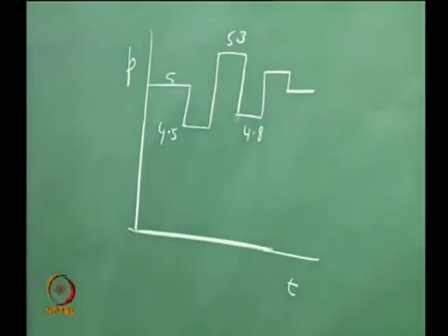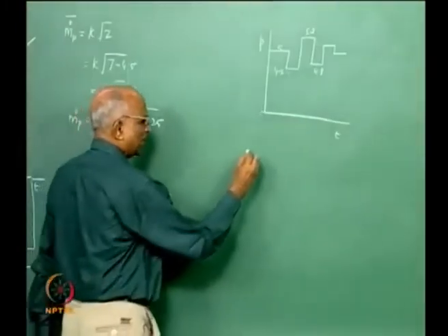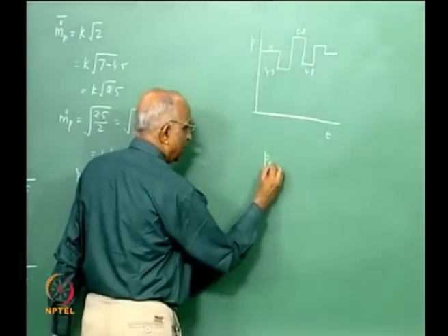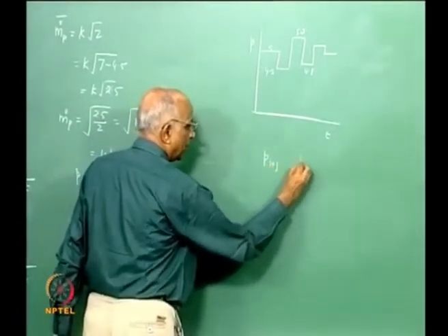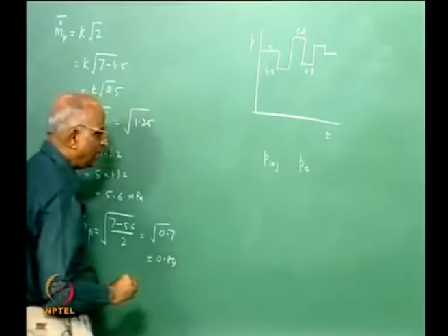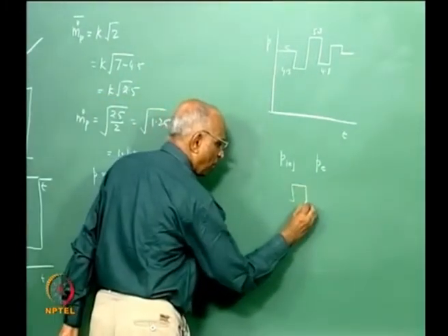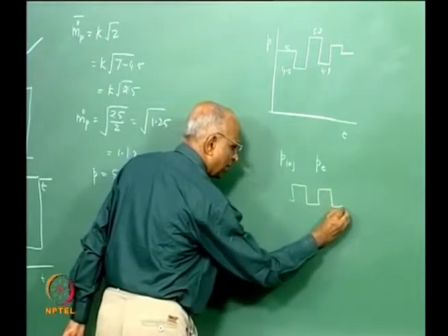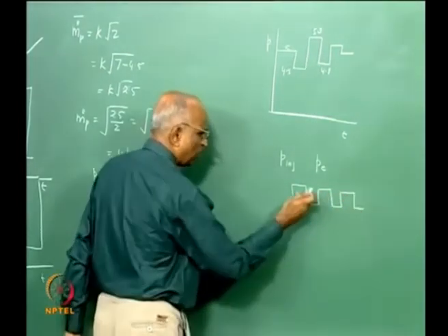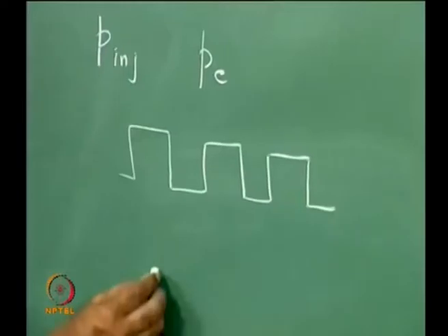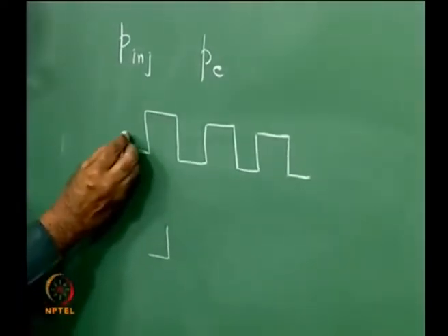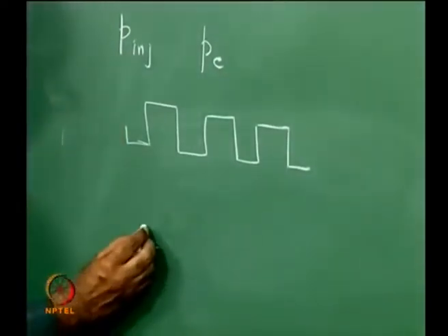Therefore, what we have just done is we have taken a simple case wherein we varied the injection pressure, kept the chamber pressure constant, and we found either the oscillations are so formed that it keeps on oscillating in a limit cycle mode, the same amplitude, or else we started with this, therefore let us start with this again.